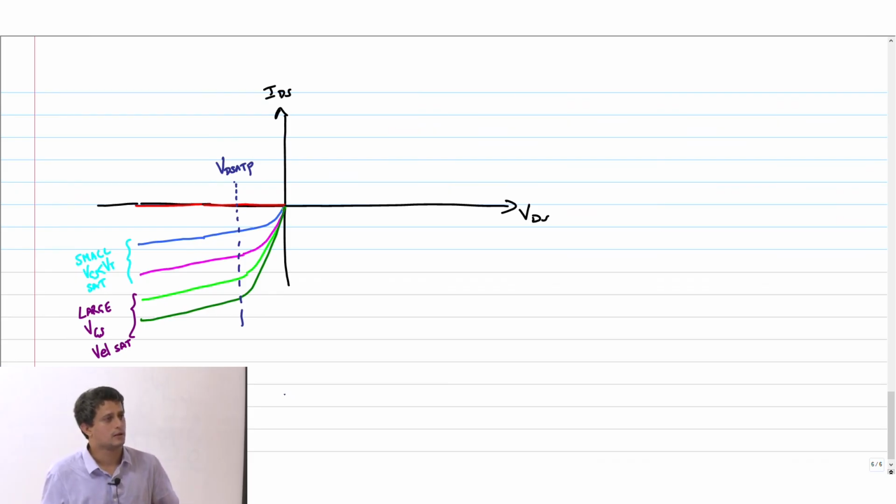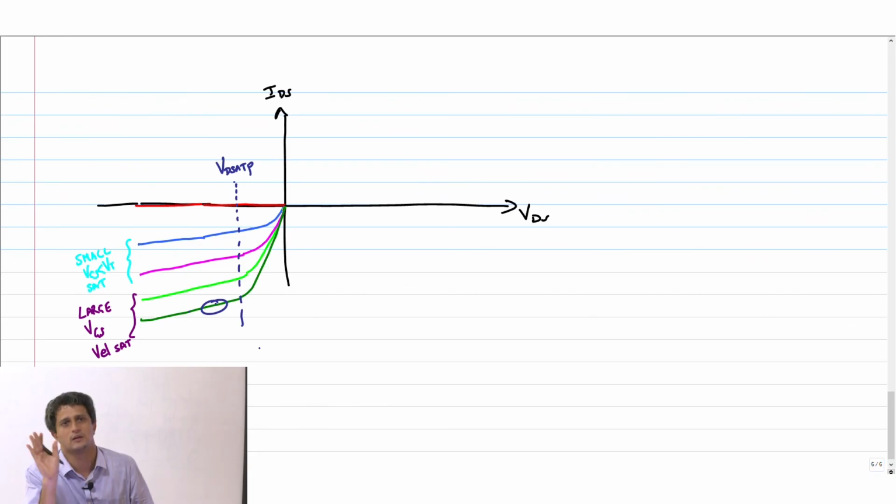And if your VDS is large enough, that means it is negative, then the current will be somewhere in this particular region, which gets determined by the VDSAT P. So that equation I have written there is mathematically consistent. Just substitute the values and you will get the answer. Don't do any conversion from mod, nothing.